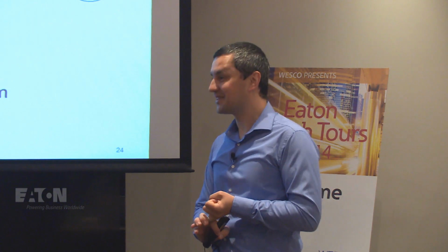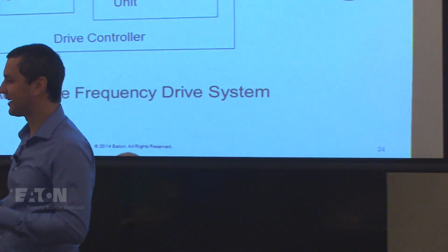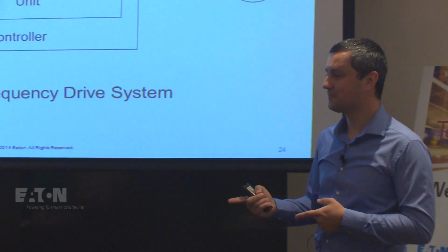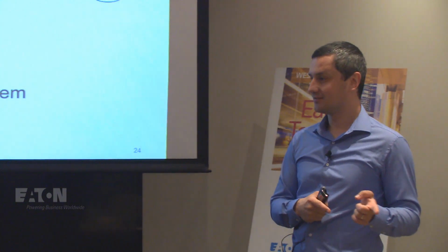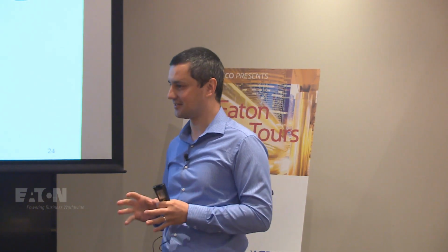Is that all the time? Can you have 1-phase input? Yes, you can. Can you have 1-phase output? Actually, yes, we can. Now we have the DC1 drive, which can do single line input, single line output. So we can control some of the single phase motors that are out there.